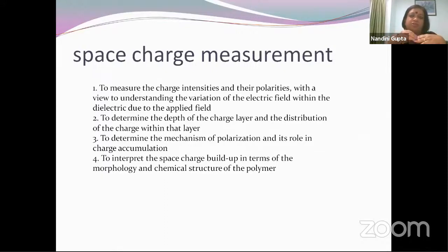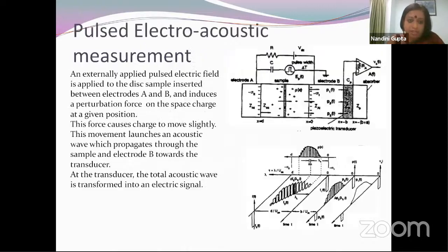The surface charge is easy to measure. Somebody asked me a question whether below threshold field we can call space charge surface charge. No, surface charge is the free charge which is present on the surface of a dielectric material. And space charge is present within the volume of the dielectric material. Surface charge would be free charge, which would have energy levels close to, or equal to, that of the conduction band. Space charge has energy levels lower than the conduction band.